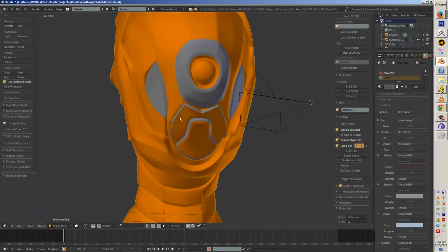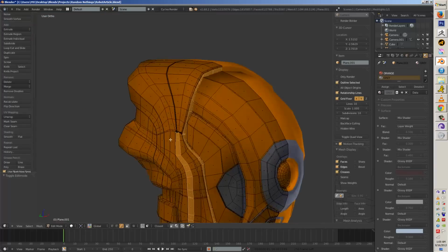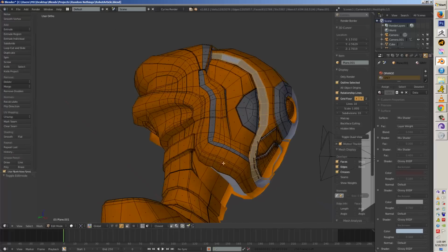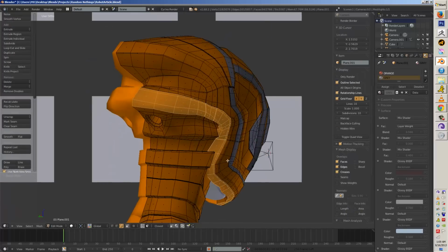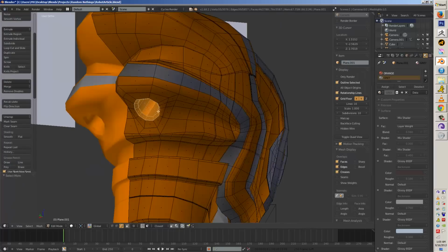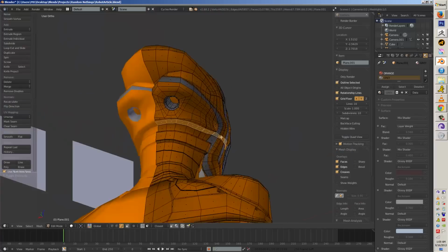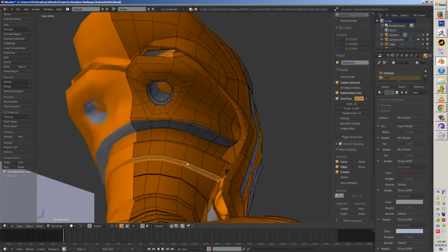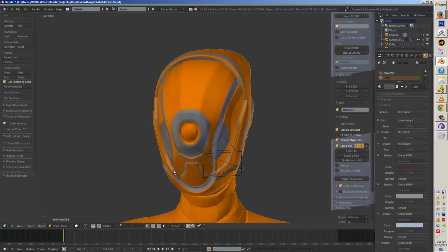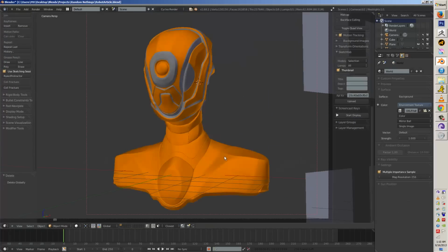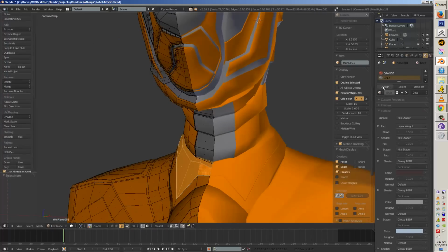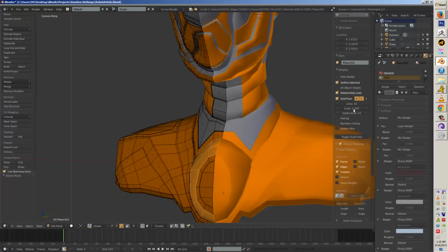I'll select something, Alt click an edge to select an edge, Control plus to grow that selection, and then from there just assign that vertex group that material. And so per material painting like this isn't really the best practice, but for hard surface stuff I find it definitely does the job, and for most models, per face, per vertex coloring is probably the easiest out of them all to deal with instead of using masks and textures, having to do it all in a node editor